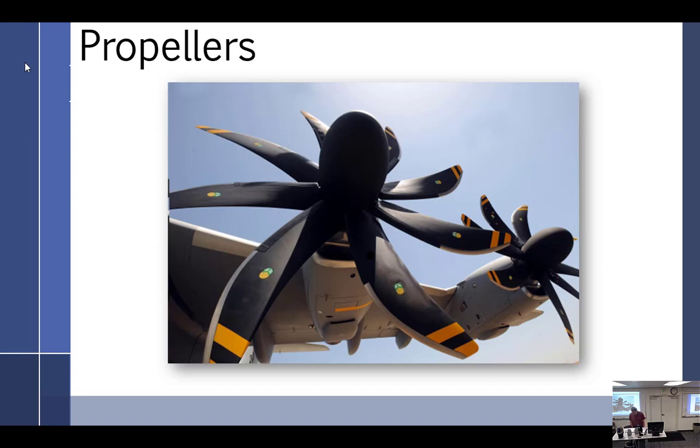The thrust depends upon the speed and the angle at which the blade strikes the air. The angle at which the blade strikes the air depends upon the speed at which the propeller is turning, the speed the machine is traveling forward, and the speed at which the air is slipping backwards. They all come into play. When any one of these changes, it changes all the rest, as they are all interdependent upon one another. Wow.